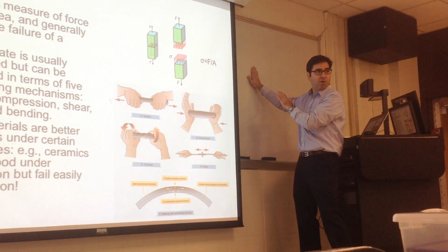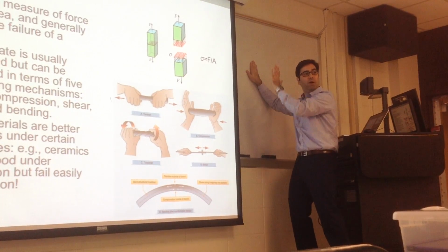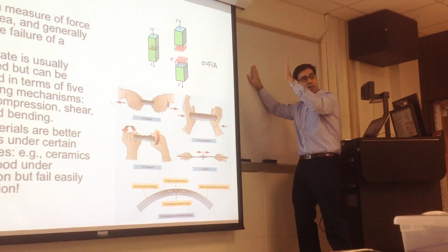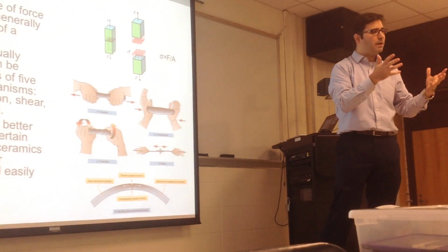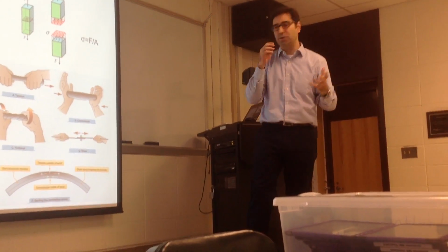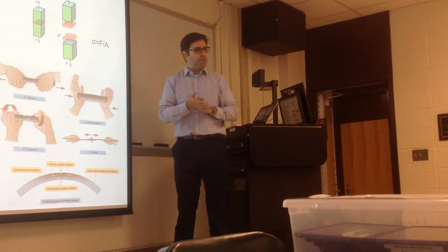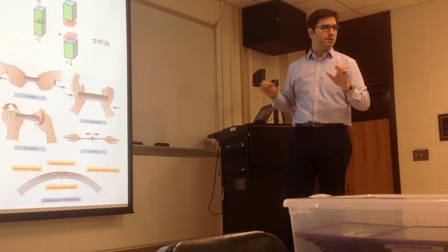So we can apply a force to this board in this direction. So we are creating a pressure, but also a component that will have the same units of force per unit area that will be tangential. So stress is a little bit more complicated, but that concept of force per unit area gives you the idea. Okay? And most loading members in structures can be understood in terms of these 5 loading scenarios.